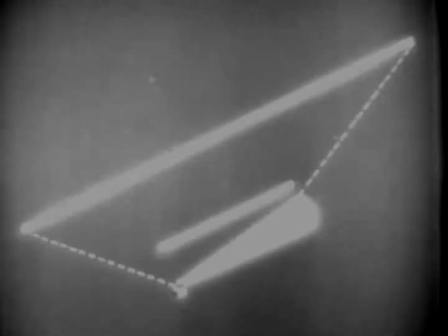When we pick up a target somewhere within that range, it's obvious that the longer the baseline we have to represent the range, the easier it will be to read our target's position accurately, right down to the last yard. However, using a horizontal baseline, this is as long as it can be, and still remain on the scope. But what we can do is stretch it out 3 times that length and put it around the edge of the scope. With this longer baseline, representing the same range that the short one did, we can read range a lot more accurately. Here's a typical circular baseline range scope, the J-scope used on the SCR 584.